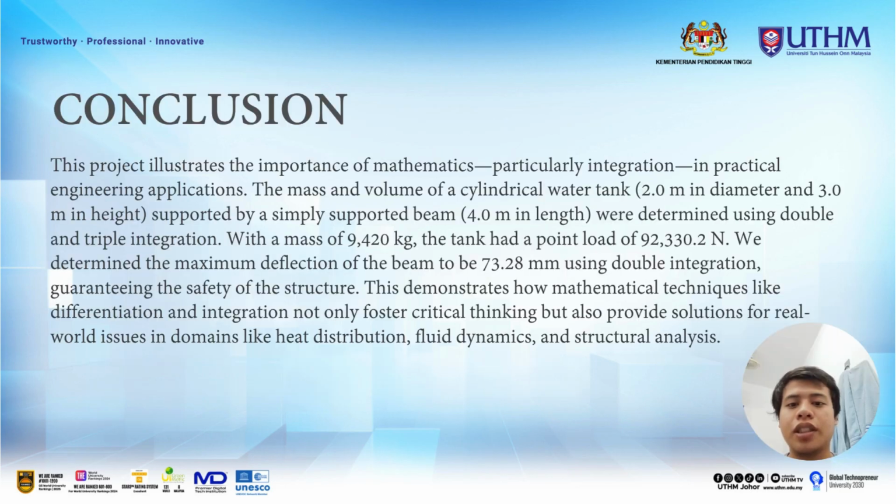In summary, this project shows that mathematics is not only useful for learning, but also important for developing critical thinking and solving real-life problems. In our civil engineering related project, we use double and triple integration methods to calculate the mass and volume of a cylindrical water tank with a diameter of 2 meter and height of 3 meter. The tank is placed on a simply supported beam that is 4 meter long and experiences a point load of 22,330.2 Newton for the weight of the water tank.